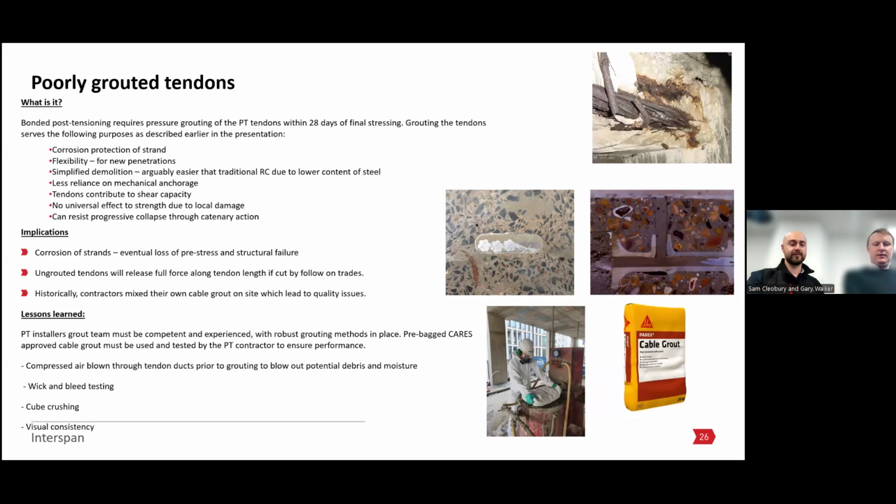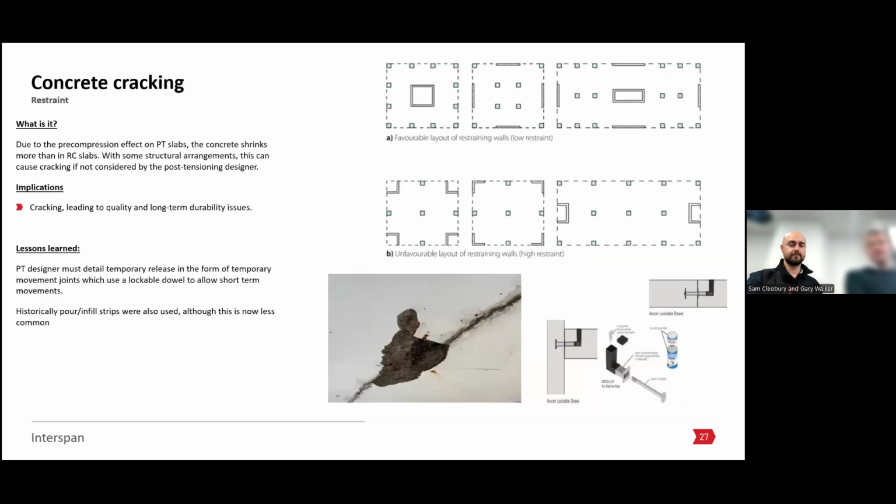Yeah, we've been called out to a few older jobs that were done, say, 20-25 years ago, where the grouting was late, or there was no CARES approval at that point, so the quality was not as good. So we've seen some issues with poorly grouted tendons that have corroded over those years, which we're going to start repairing. So it emphasises the key quality systems that we've brought in.